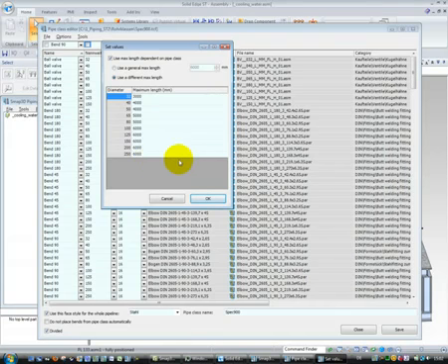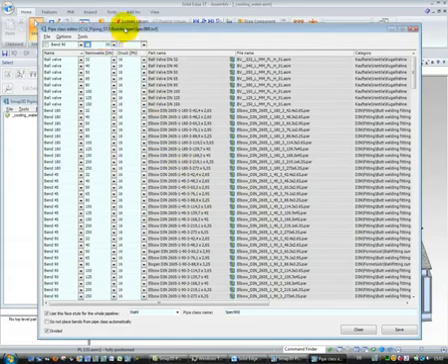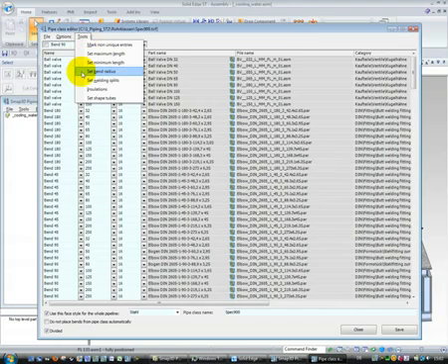Should there just be a welding split between one tube and the other, or should there be no welding split, or for example should an additional component like a coupling or a screwed union be placed, and so on. All such behaviors we can control with these additional settings in a pipe spec. For example, the setting of the bend radius allows a user to define if he would like to have bent tubes instead of the placement of elbows and bend fittings.